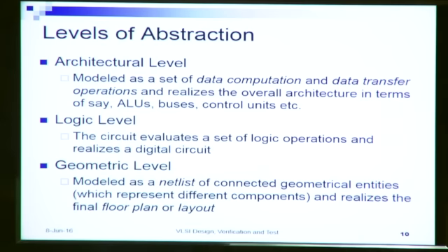This functionality in terms of data computation and data transfer is then realized in terms of the architecture, in terms of ALU, buses, control units. So these operations will be realized in terms of an architecture of the design. From the operations, we will first get an architecture of the design at this level. The architecture will be in terms of the ALU units, buses, how they are connected, and there will be control units that control operations at each time step.